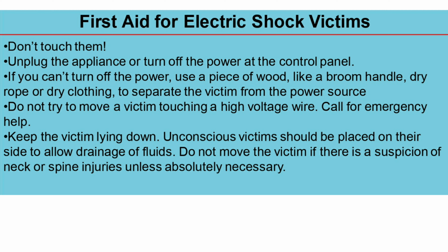First aid for electric shock victims: don't touch them. Unplug the appliance, or turn off the power at the control panel. If you can't turn off the power, use a piece of wood, like a broom handle, dry rope, or dry clothing, to separate the victim from the power source. Do not try to move a victim touching a high voltage wire. Call for emergency help. Keep the victim lying down.